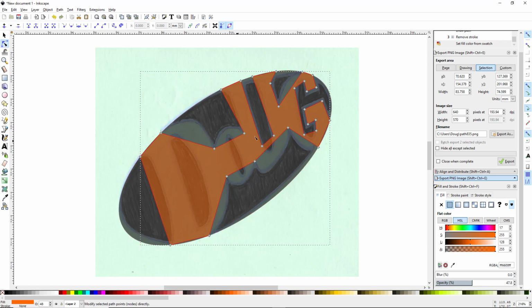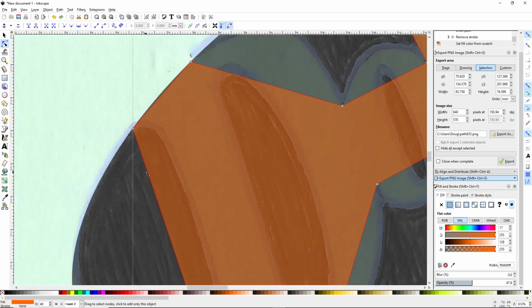And now you can see all these spots. These are all the spots where you click to create a new line, and those are all areas that we can adjust the shape of the line and where the corners are, and we can get this thing to the exact shape we need it to be. So let's start with the top of the D over here, hold Control on the keyboard, and then scroll up on the mouse wheel so we can get a better idea of what we're doing here. Now any area that's over here at the top of a letter where it's going to be cut out of the ellipse, we can just hover over the line until you see the hand, click, and then you can just drag that up. It doesn't have to be right on the line.